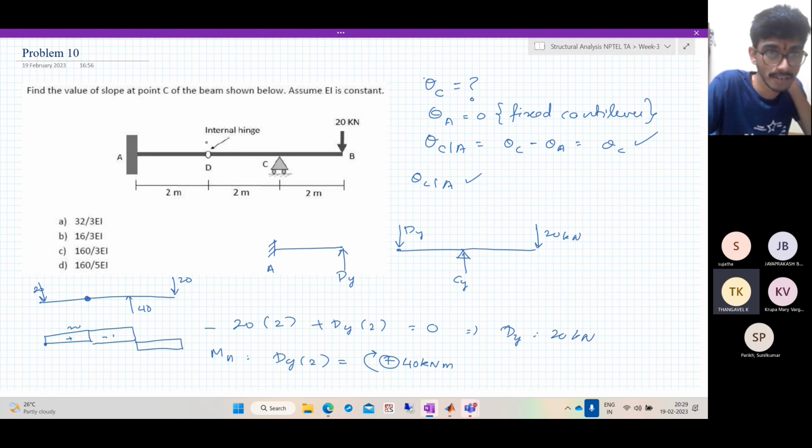So until this point, at the point C, if you see, the deflected shape will be something like this. It has an upward force. It will be something like this. And at this point, the slope is no longer continuous. Beyond this, it will have some other slope. So since the slope is discontinuous here, we cannot find its derivatives, which are the shear force and bending moment. It is 0. So let us do it from this set.